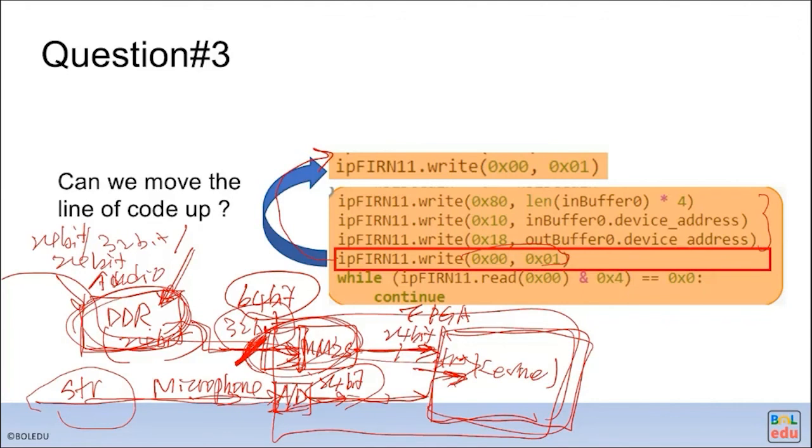So if we are designing for another bit width which is not 32 bits, we need to design another part of the hardware to translate from 32 bits to the bits we want? Yes, you can do whatever. Like Xilinx provides a VDMA IP. You can look up the VDMA, and it is very flexible.